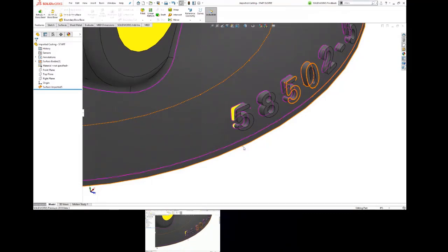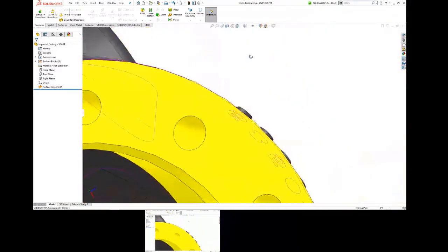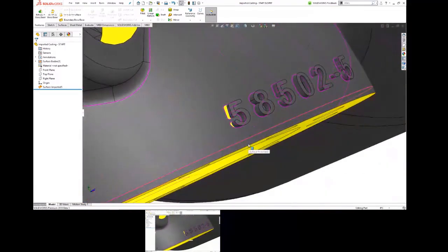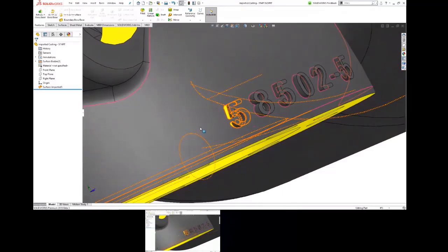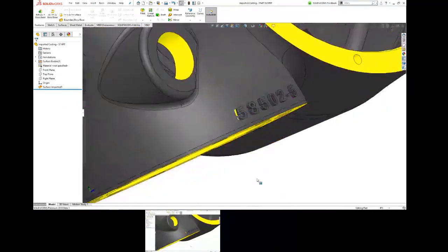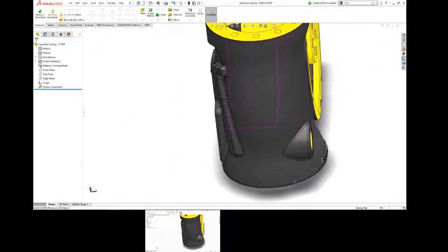But if they are inside, it's still probably going to require a little bit of sleuthing, because it'll zoom in on it, but it can't zoom inside the model. So you'll see it's there, but it's inside. So you might have to do some intermediate delete face operations to try to sleuth your way inside that. Yeah, not 100% straightforward.